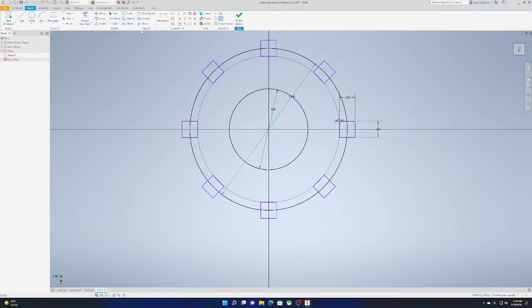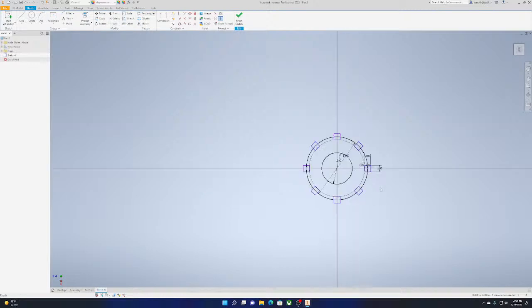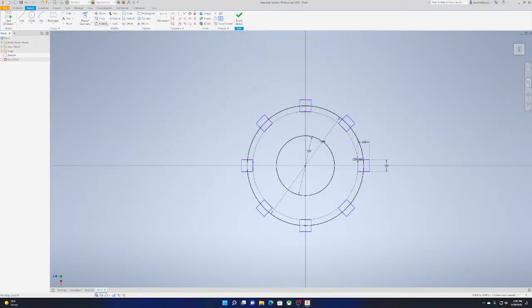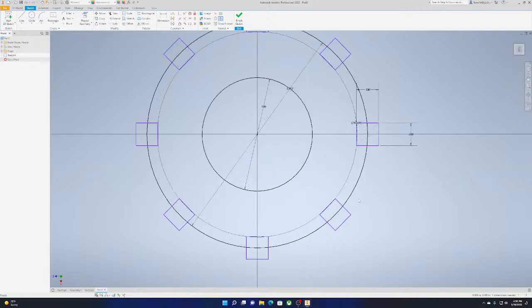No one really uses rectangular pattern as far as I'm concerned. It's whack, but a lot of people do use the circular and mirror tool. With the mirror tool, I can say extend. I'll swap this rectangle. I can say extend this to the middle. I can add my axes, so I'll just draw a line right here. It doesn't really matter. And then for the mirror tool, I select which edges I want to keep.